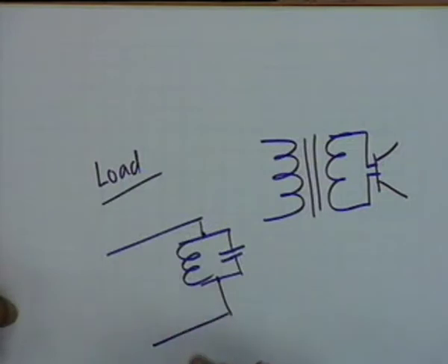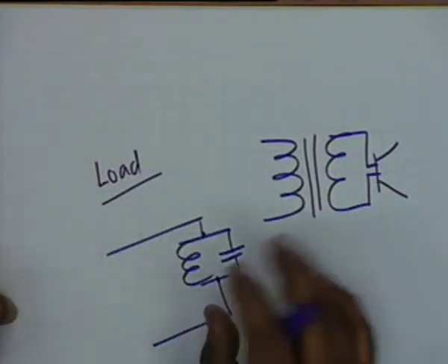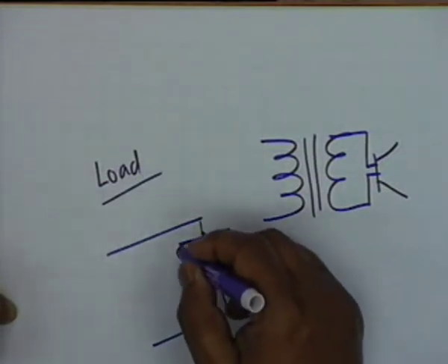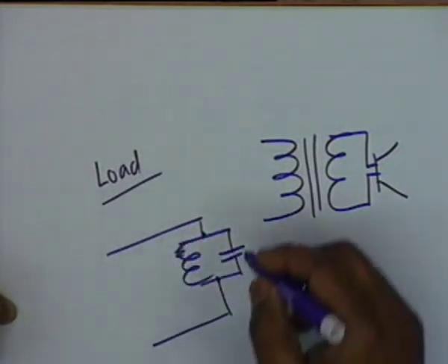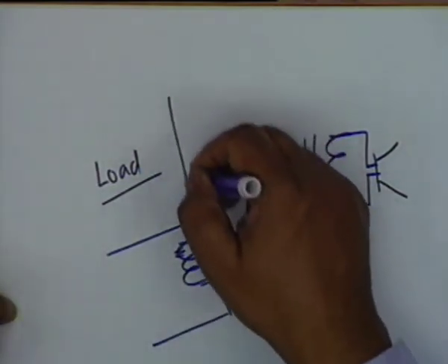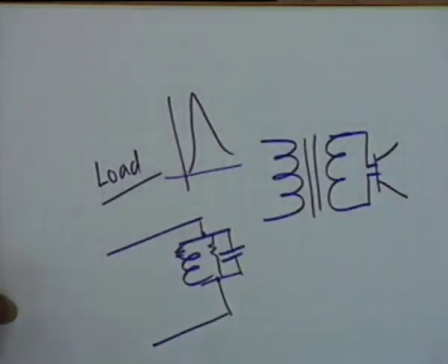And therefore, you will see later that the gain of such an amplifier is proportional to the load, and therefore you expect infinite gain from this. Actually, you don't get infinite gain because the inductance has a resistance, the capacitor has a resistance in parallel, and therefore you can get a large gain. Alright, and that's how you get a characteristic like this, a tuned characteristic.